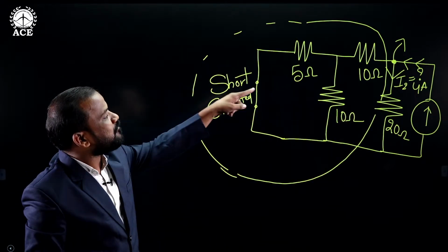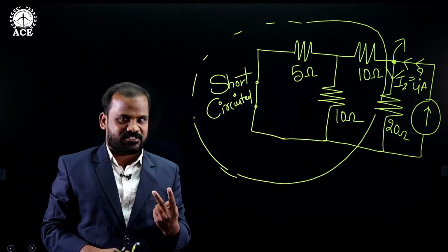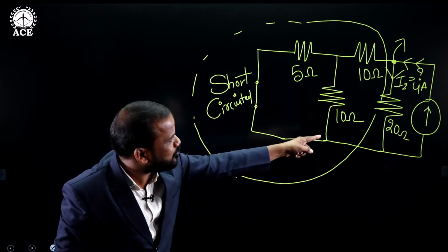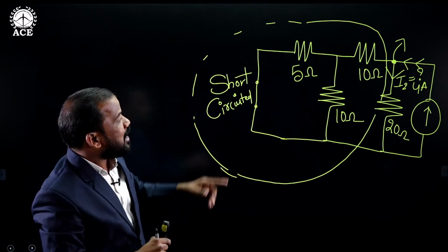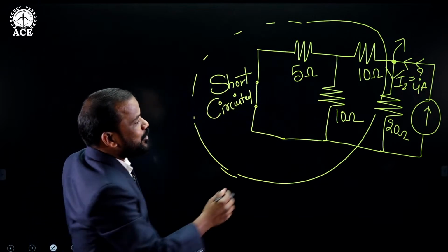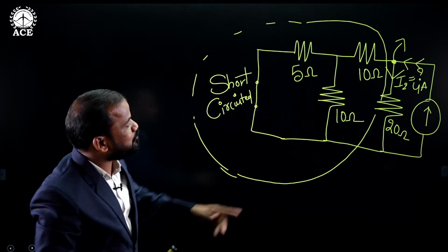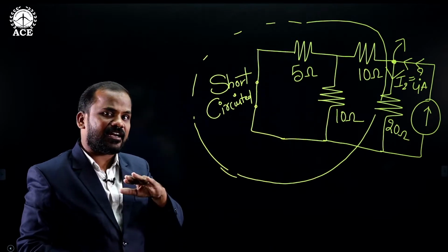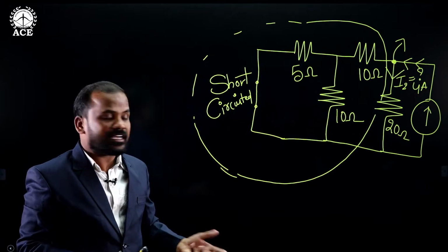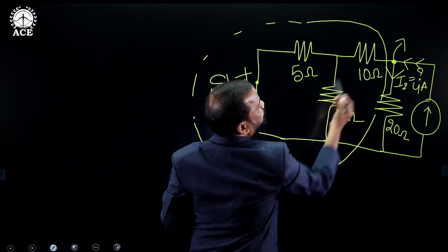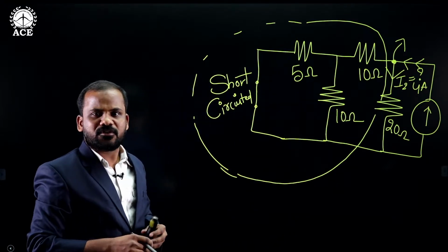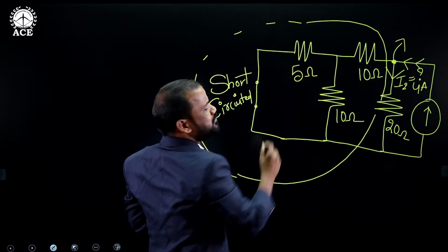It means after the junction point we have two branches. One is the combination of this complete resistance branch, and one more is the 20 ohms. Now, out of 4 ampere of current available at the junction point, how much current is flowing through that particular 20 ohms, you can directly find with the current division rule. But how to consider the opposite resistance? Can I directly consider 10 ohms? No. Can I directly consider the combination of these two 10 ohms? No. Can I directly consider the 5 ohms as opposite? No.